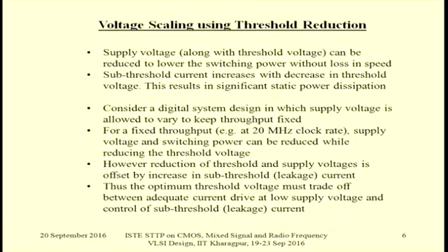Now, after energy delay product, what we want to discuss is voltage scaling using threshold voltage. Again, if you remember the expression, current varies directly with (VDD minus VT) whole square, and when you take the time, throughput is our premium, so throughput is inversely proportional to (VDD minus VT) whole square. Now, if you reduce VDD as well as VT, you will see that the speed can remain constant. But if you decrease VDD, keeping VT constant, then the delay can be increased.